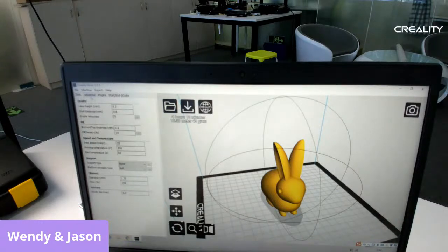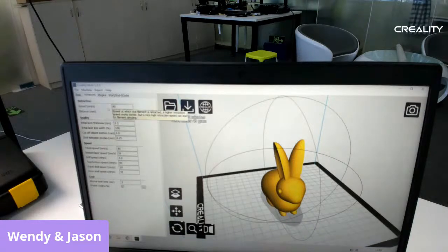If you want to dig in a little bit deeper, go into the advanced. From here, it shows you some settings we do not change that frequently. It shows you the retraction speed, so how fast the hot end, the nozzle would pull back. It shows 80 millimeters per second. I'm not pretty sure, but that sounds okay to me.